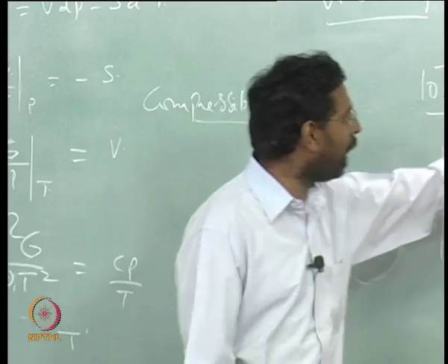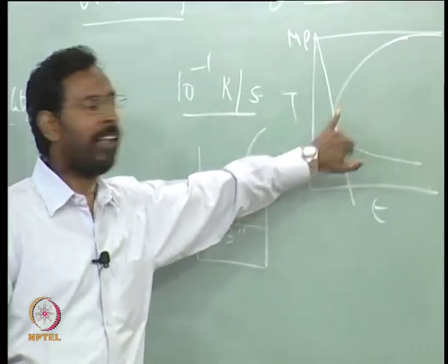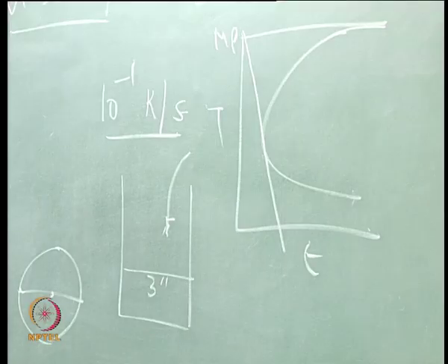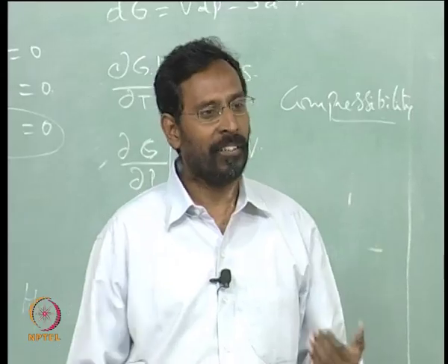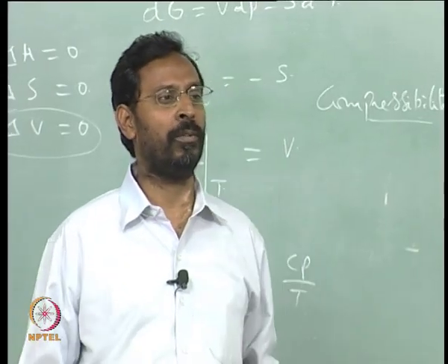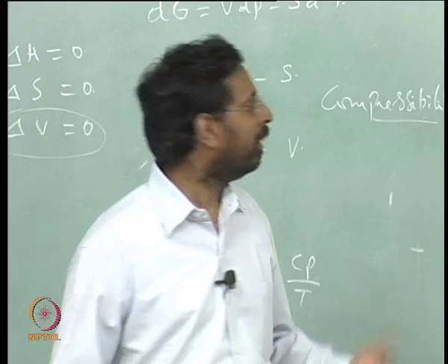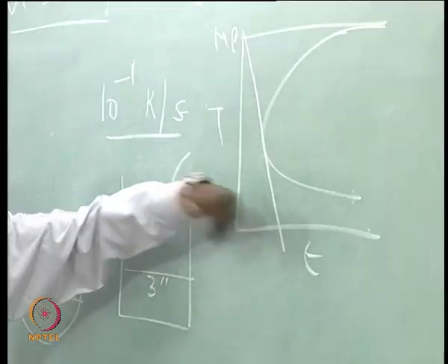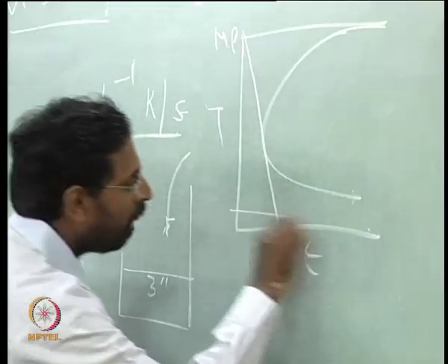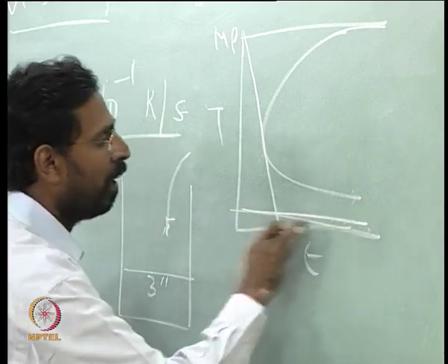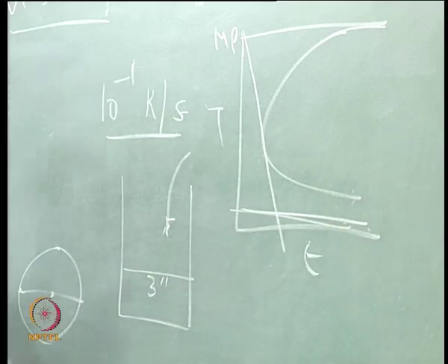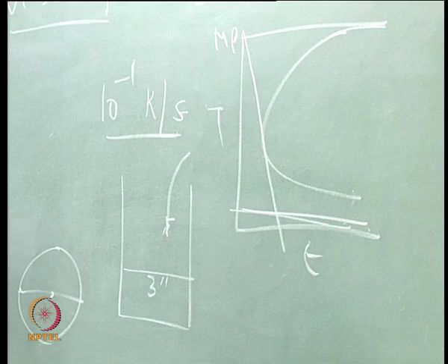In principle, for any material, as long as I have a TTT diagram generated like this for a liquid to solid transformation, I can always find out what cooling rate is sufficient to suppress crystal formation, so that the liquid remains liquid until you reach a temperature here, which we called Ms in the case of martensite transformation, and we call here Tg.